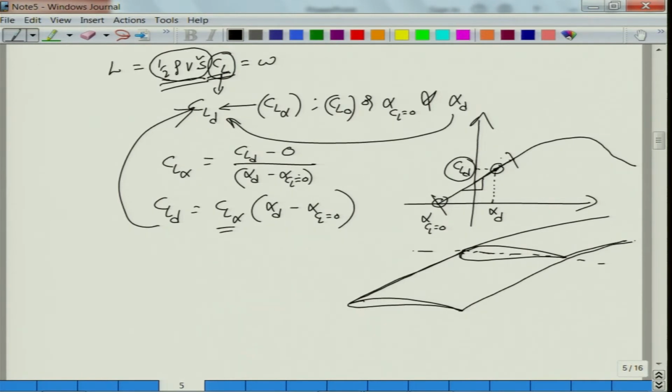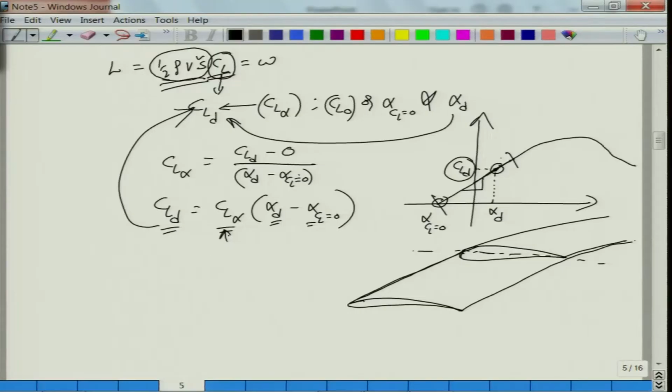By doing so, the CL alpha varies, because you know CL design, you have fixed alpha design, and you make these two the variables of the iteration. So, you can find out the corresponding CL alpha. Once you know CL alpha 3D, you can find out CL alpha 2D, because you know the aspect ratio and you know E based upon the previous discussion. We have developed the previous subroutine for the planform selection. From there you figured out the aspect ratio and E. Then using those two values as input here, you can find out CL alpha 2D.